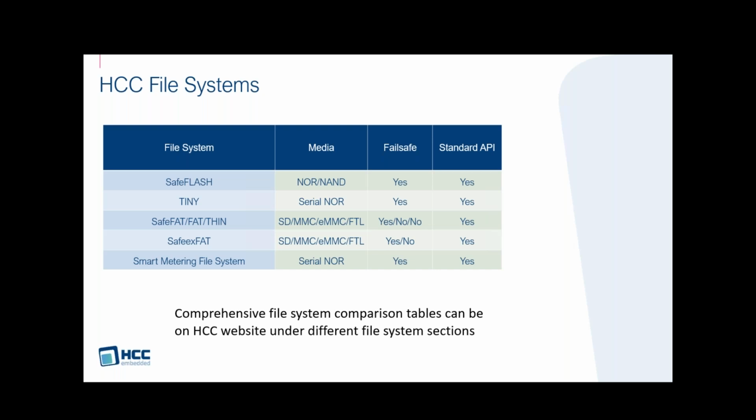Another big advantage of that particular system is it comes with modeling software so that you can actually run your use case in simulation on a PC before you go anywhere near your flash chip, and you can see how writing the records over a period of time will wear the flash. You can then tune the size of the flash you need to use and the type of flash you need to use to get the best possible result.